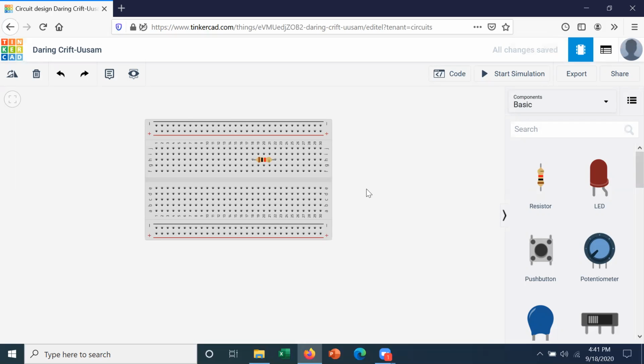part of the experiment, I've made the measurement of the resistance, and I've looked at the color codes. Although in that video, I think there was a mistake. I think I said a 12,000 ohm resistor was red something or other, when actually it should be brown red. The brown and the red were very difficult to see. So anyway, you're going to be starting doing your experiments.